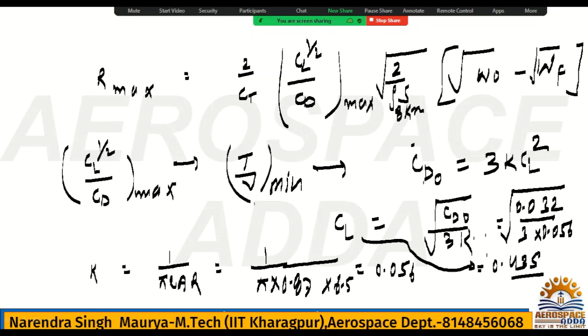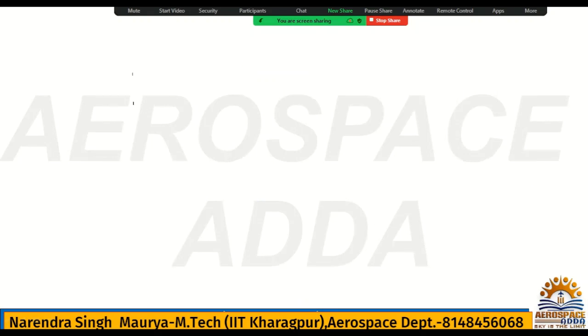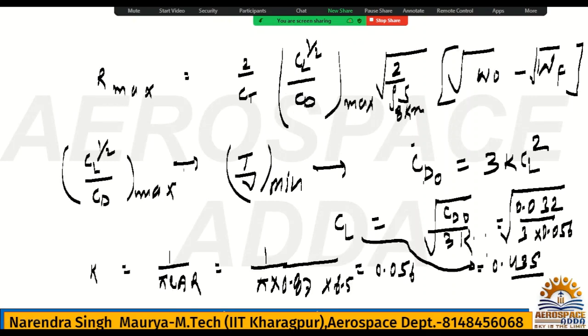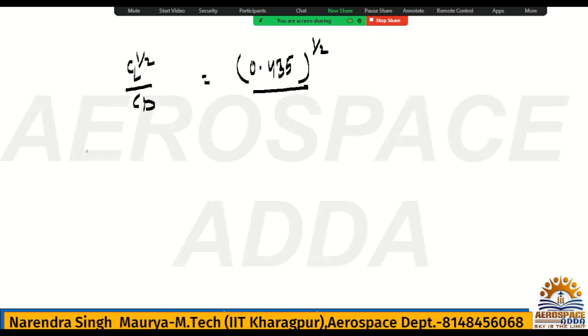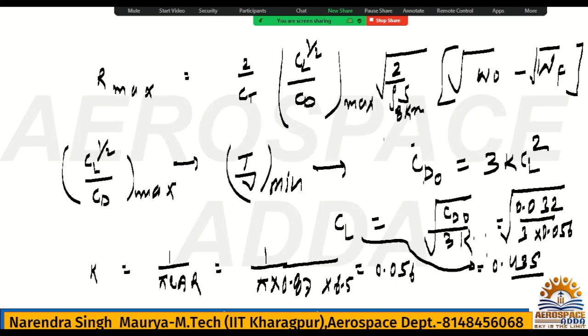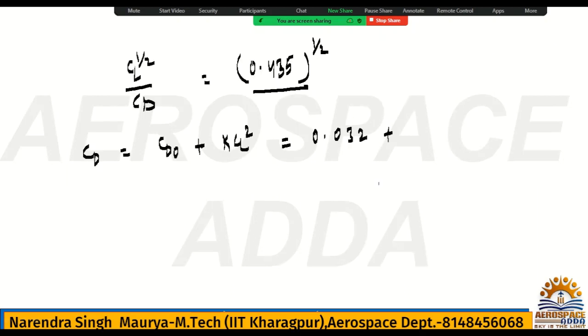Fine. So if you write CL to power 1 by 2 by CD value, what is the CL to power 1 by 2 by CD? What is the CL you have calculated? It is 0.435, whole power 1 by 2 divided by, what is the CD? If you remember, CD is nothing but CD naught plus KCL square. What is the CD naught here? It is given. What is the CD naught? 0.032 plus. What is the KCL square? Check. KCL square is nothing but CD naught by 3.